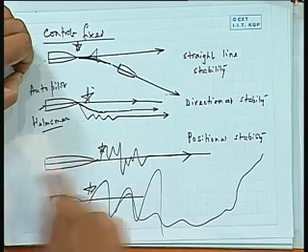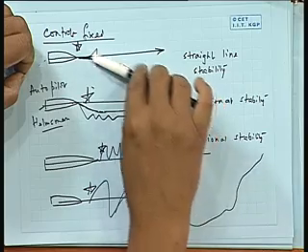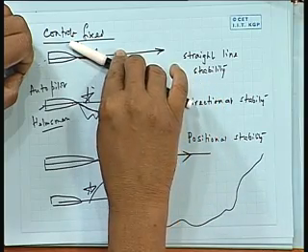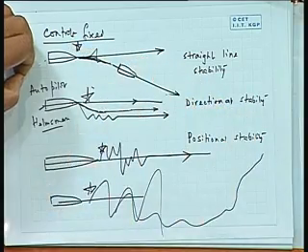There are various measures of extent of stability, because they get corrected by this. You can also see that if the ship has very strong straight line stability, that means it always wants to maintain a straight line, then it is difficult to turn it. It means that the rudder is fixed in one direction, not moving. Or it does not have a rudder. You can say the controls are not operating, you may not have a rudder.